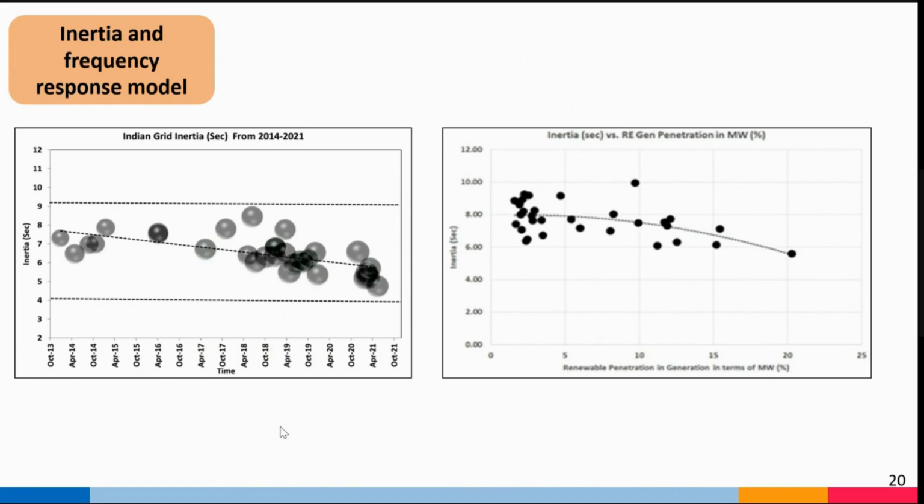In the swing equation, you know how much generation is lost and what the total inertia available in the system is, like the MVA, how many units are coupled. So what is the total MVA available in the system at that point in time, the synchronous MVA basically, not all the MVA, only the synchronous part.